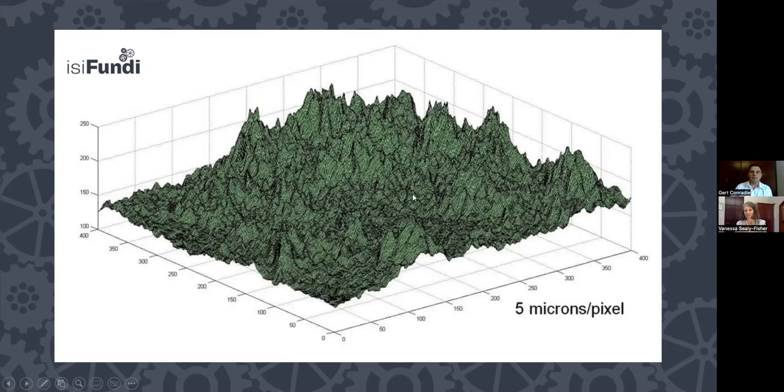And this is the reason for putting on the anchor profile, whether it be an angular profile, as you see here, or a peened profile if you maybe shot blasted the surface. And that's the reason to want to record these. I know that one of the ways we can measure the profile is by using a profile gauge. And another way that I think many people are familiar with is replica tape.